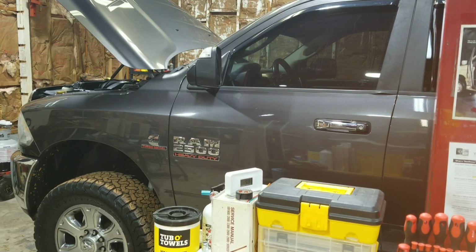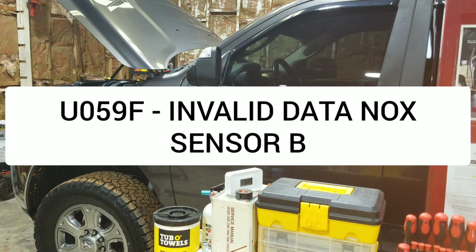Hello everyone. Today I'm working on a 2014 Ram 2500 four-door quad cab pickup truck with the 6.7 liter Cummins turbo diesel engine. I have a check engine light. The code in the engine module is reading U059F, and that comes back as a NOx sensor, NOx sensor B, invalid data. So I did some research on that.